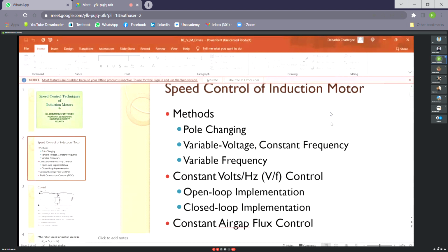That means if you design the rotor and stator with different numbers of poles, naturally you will not get any steady torque, only pulsating torque, which results in no rotation or in pulsation and jerking. So the number of poles for the rotor and stator windings has to be made the same. That is only a concern for wound rotor machines because there we are making the windings. In cage machines, there is no such question, because the rotor poles are created by the stator poles, and they automatically assume the same number of poles as the stator, based on the design of the bars, number of bars, etc.